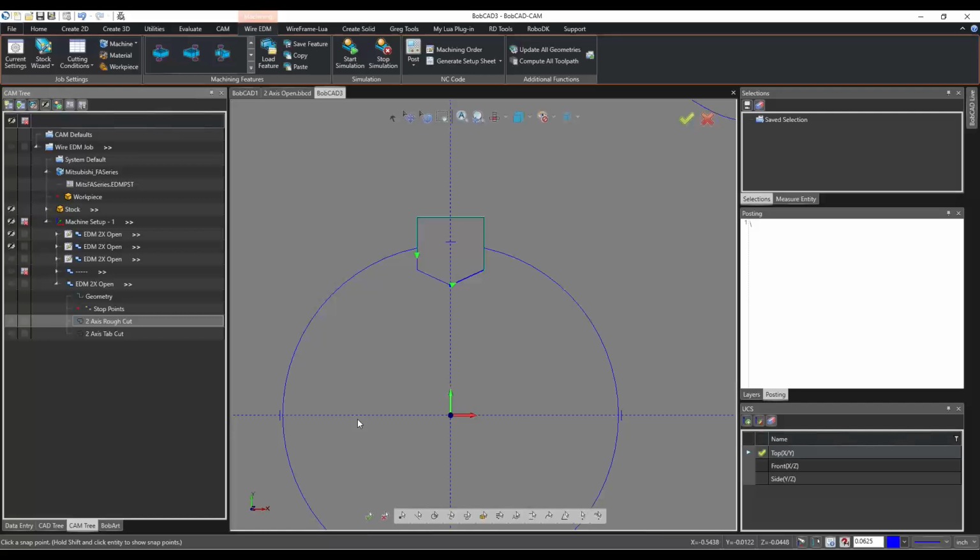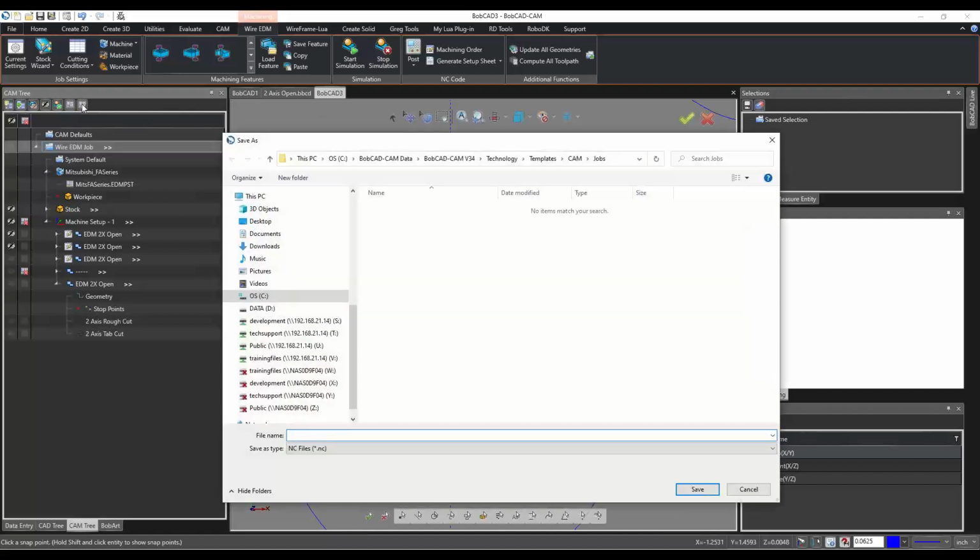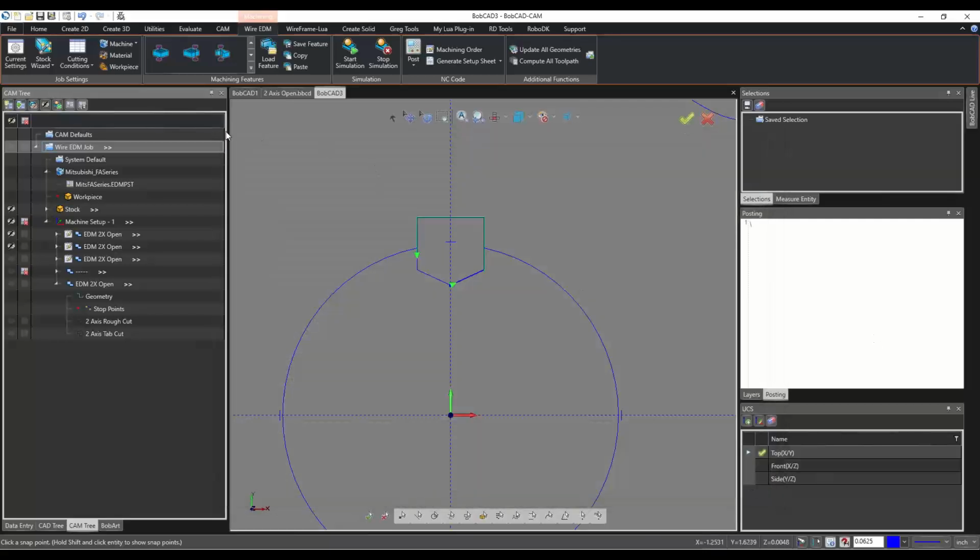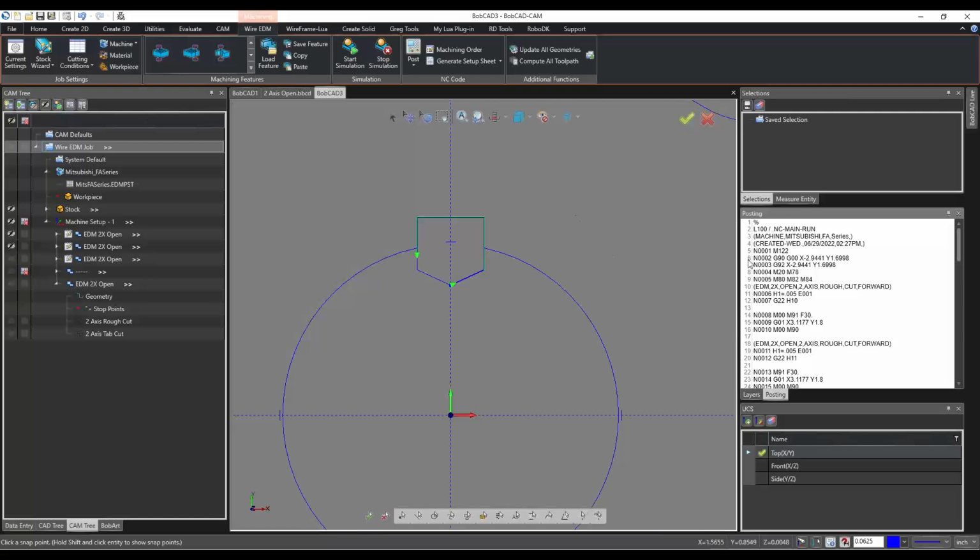And yeah, after you get all the toolpath that you want, then you just post out the code. So to do that, there's just a little button up here. So it's the first button, or the furthest button over, is post and save as. So if I click that, it's going to immediately save the file. What I personally like to do is I like to see the code first before I save. So I'll go the one to the left over, click that. And then as you can see, it shows up in the posting window here. And you can just verify everything, make sure everything looks good.